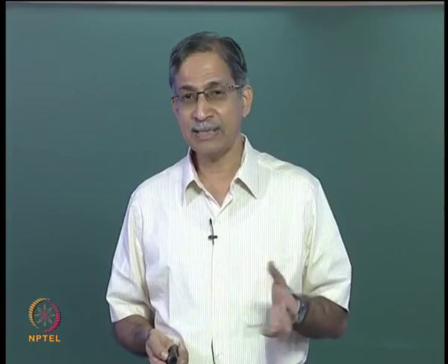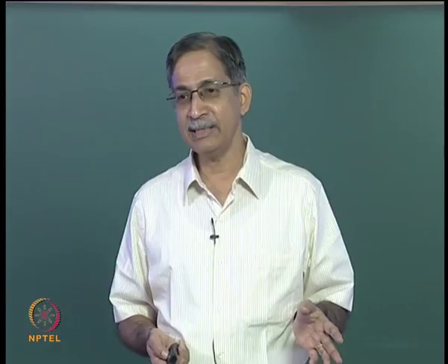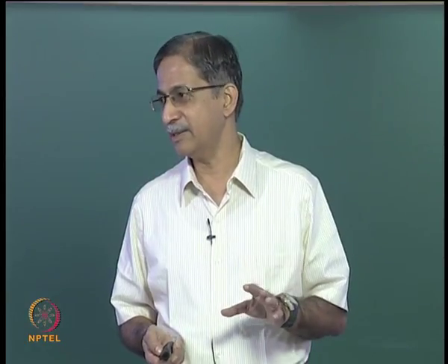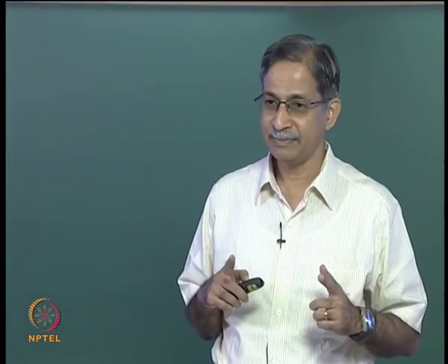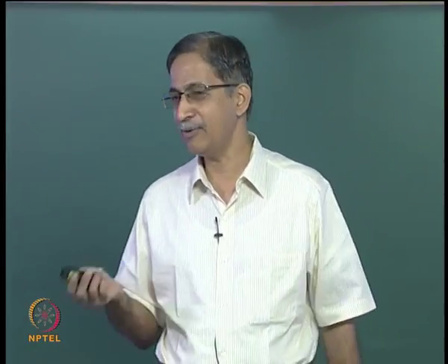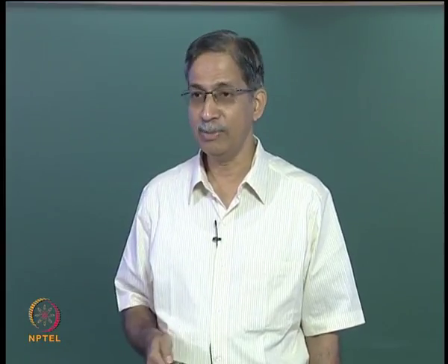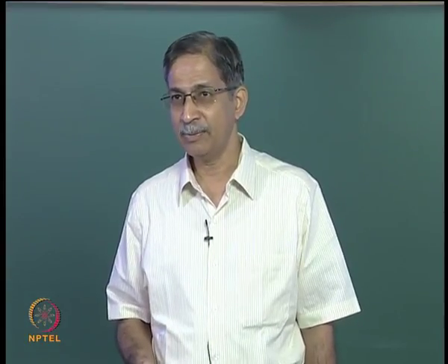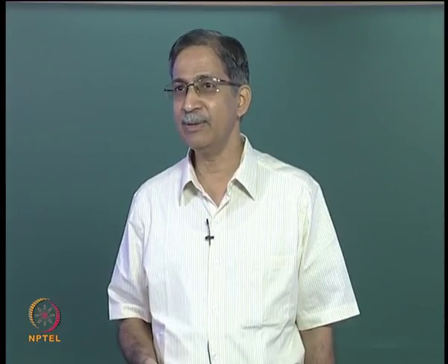We will expect some difference between ignoring axial deformation case and including axial deformation case, and that will be a little more pronounced when you have sloping legs. Okay, we will see that. Apart from that, you should get the same answers we got when we did the slope deflection method. Okay, so we proceed, we write down the element and structure stiffness matrices, very easy to write down.